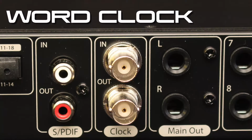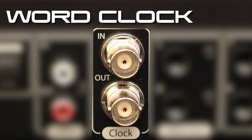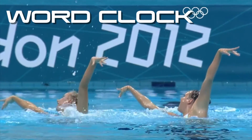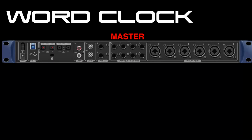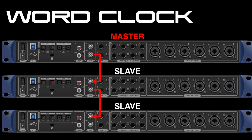Many larger interfaces include two connectors on the back labeled clock, word clock, or sync. The clock in and out connections are used frequently in larger systems that incorporate multiple digital devices. Digital devices must work together in perfect sync, all moving from sample to sample at the same rate and perfectly in time. If the devices aren't perfectly synchronized, there'll be pops, clicks, and dropouts in the audio. The clock connections need to be connected together with one device designated as the master. When all is well with the system, each device follows the master clock, sample for sample.